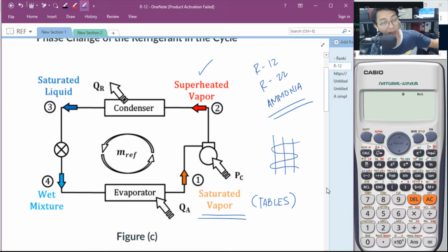The same goes for our air conditioners. We have condensers there, the ones that sweat. It means the heat absorbed by your refrigerant is taken out of the system passively by air. Now, in bigger systems, refrigeration systems or cooling systems, we use cooling towers. Where we have a water basin, used by the condenser to cool itself, and then that water will be evaporatively cooled, using heat exchange between the water and the air.